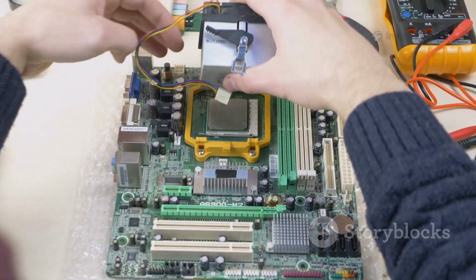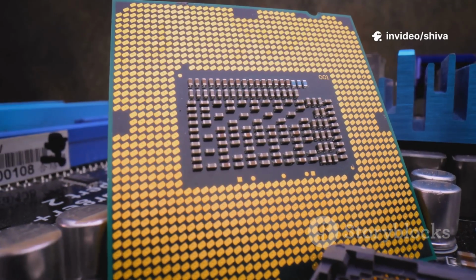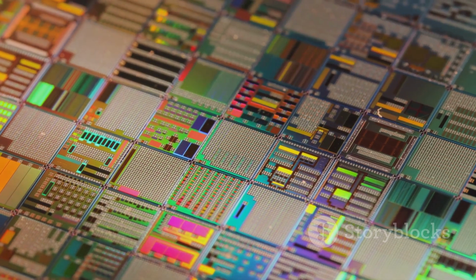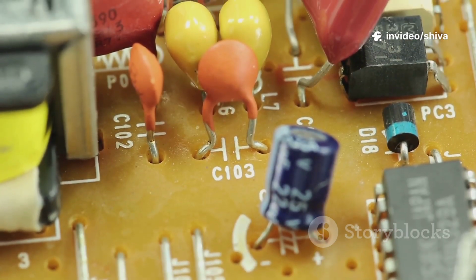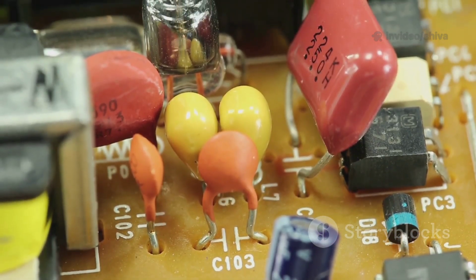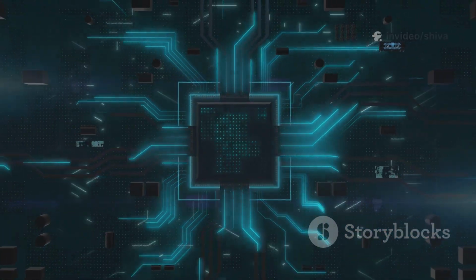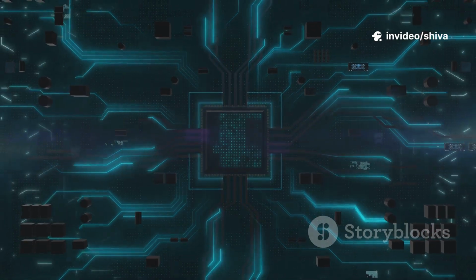Now, let's put it all together. The part of the computer's processor that does all the math and logic is called the Arithmetic Logic Unit, or ALU. The ALU is like the calculator part of the CPU's brain. It contains circuits like our adders to perform addition. It also has circuits to do subtraction, which is just a clever form of addition, as well as circuits that perform the logical operations we learned about, AND, OR, and NOT. When the CPU needs to calculate something, it sends the numbers and the command, like add or compare, to the ALU, which uses its specialized circuits to get the job done almost instantly.